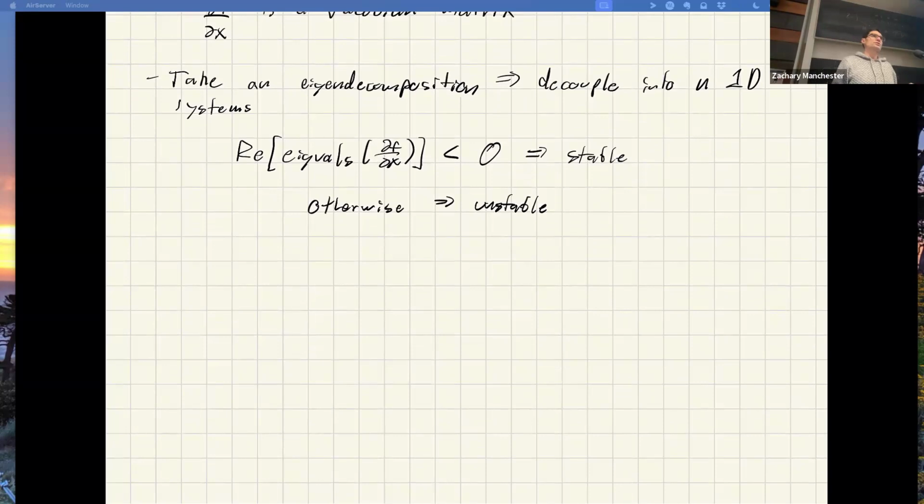Yeah, so what that corresponds to is they're more damped. So if they're more negative, farther to the left half plane, it basically means in time, the energy in those modes is going to get damped out quicker. So that kind of corresponds to how fast they'll return to the equilibrium point. Does that make sense?